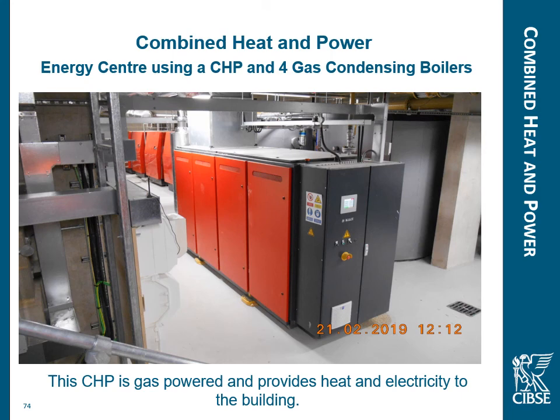Here's an example of one in a development in central London. It's a combined heat and power in an energy centre using a CHP and 4 gas condensing boilers. Now the gas condensing boilers are obviously quite efficient, but not really efficient enough to satisfy building regs compliance. So what the developer has done is put in a combined heat and power, because that ticks a box for building regs compliance.